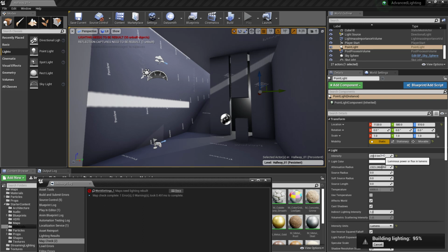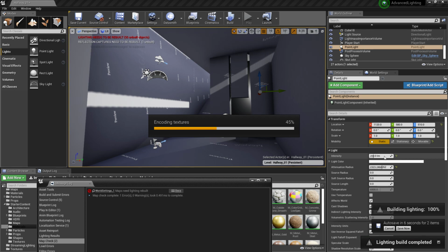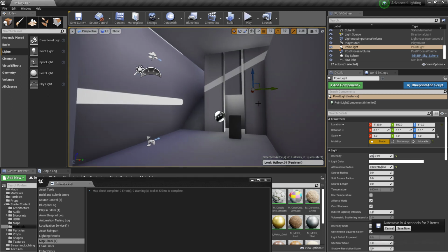So if you're working with a really big space, it'll feel really unintuitive because these bars only go so high, like 1200 or 1800 lumens. But a football stadium light is like 200,000 lumens. So don't be afraid to come in here and physically type in 200,000. Oops, kind of moved some stuff.